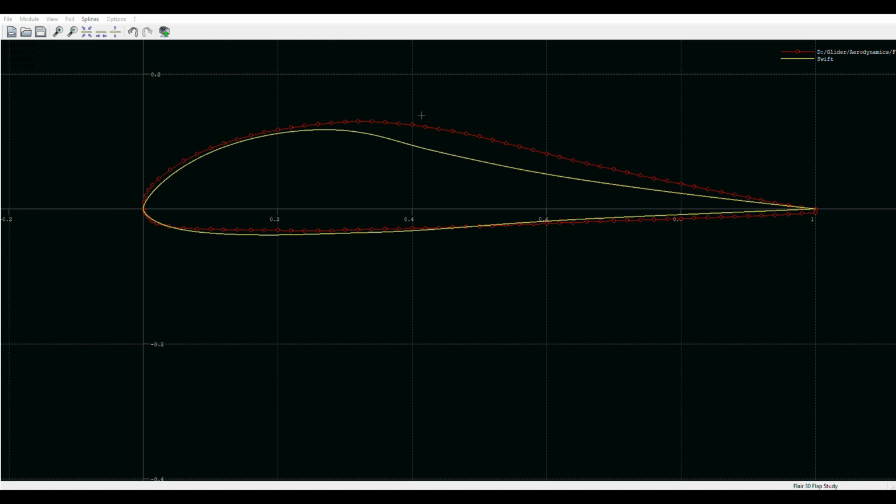So Swift, Flair 30 share some characteristics. They were probably both generated using the same methodology, maybe even the same code. These are airfoils that are generated by, you set up a code saying, here's what I want. I want this kind of CL, I want this drag, I want this kind of pressure recovery, yada, yada. You put in those parameters and it draws the airfoil for you. So this airfoil will perform and deliver those characteristics. I know that was used for the Swift. I would suspect it was used for the Flair. It's very popular at the time to design airfoils that way.